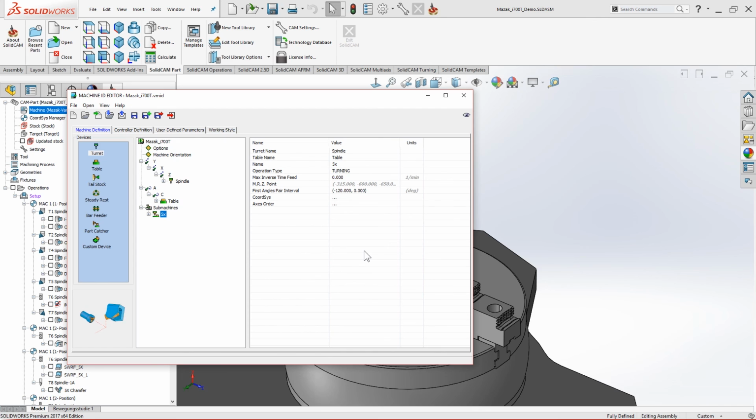to do turning. But pay attention that this parameter is directly connected to the machine operation type. So that means if my machine can only do turning, then my submachine can only perform turning. Only if my operation type is set to milling and turning, I'm allowed to control whether my submachine will be capable of milling, turning, or both. In this particular case, I will use both.